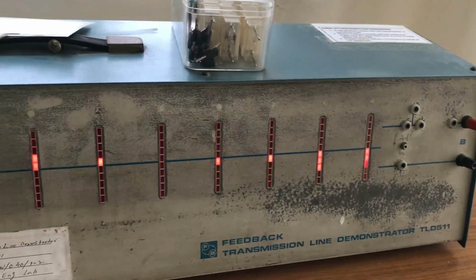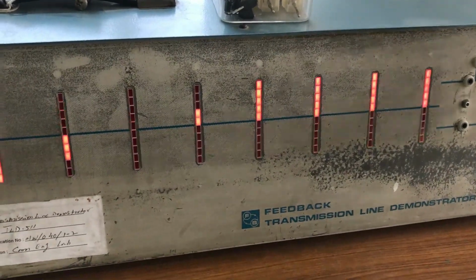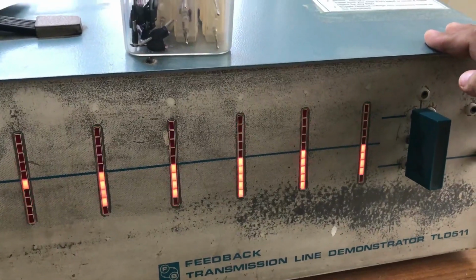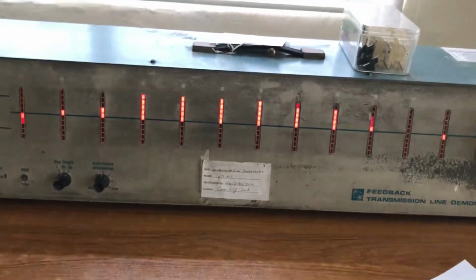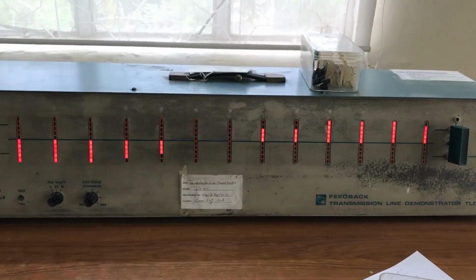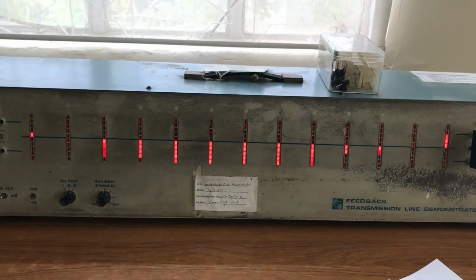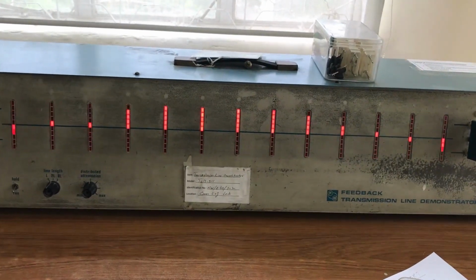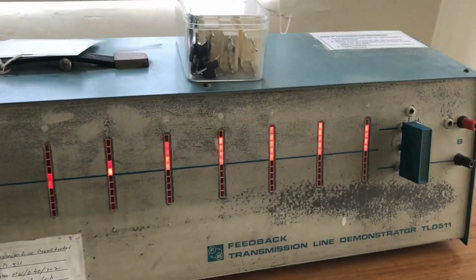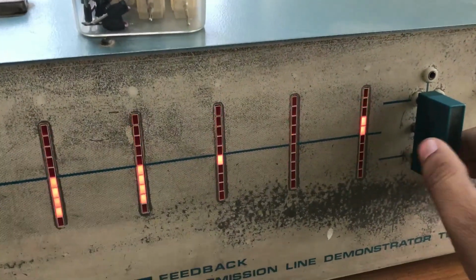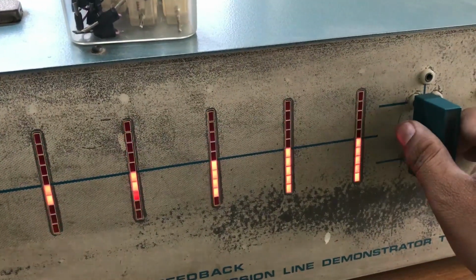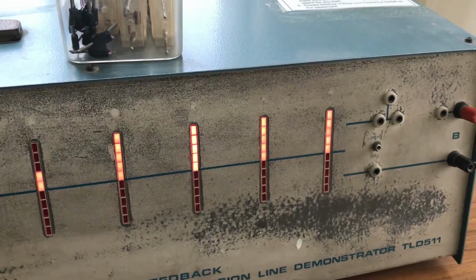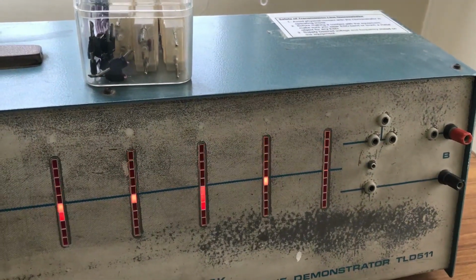All right. For a load that is matched, this is the pattern you should observe. That entire thing is being absorbed by my load. You need to visualize this a little bit. Now at the end, when I make this an open circuit, as you can see right here, this is the place where you need to observe. As soon as I remove this, I can see the maximum voltage at the end of my transmission line.